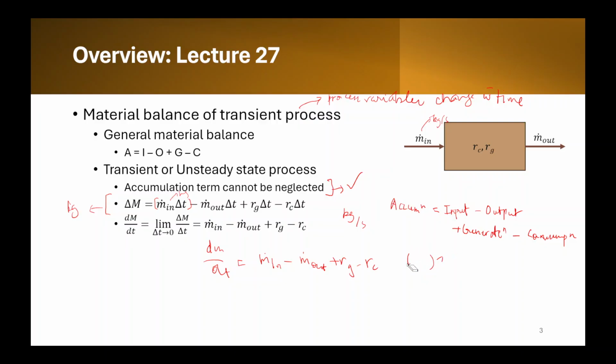But a rate of anything, suppose the rate is given as kCa, has the unit mole per liter second, so it is already with respect to time. That's why I have not written the dot, as we have written in m dot. Some people write it as r dot g, but I have written rg only.